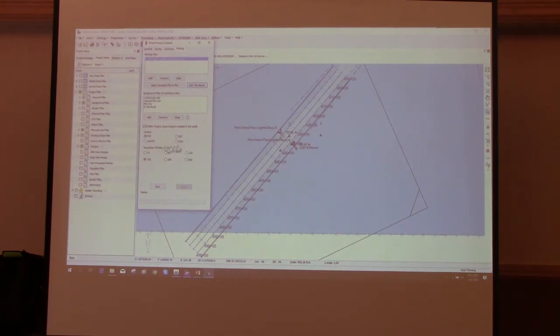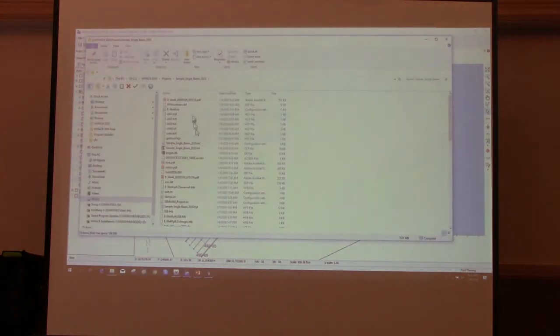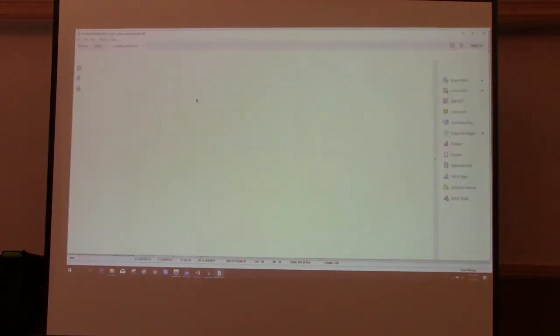So I could send it to PDF, GeoTIFF, DXF, or DWG. So let's do a PDF right now, and I'll do 150 dpi, and click on Run. So it's running through the sorting processes and then the contouring and then finally generating a plotting sheet. So process complete. I'm going to leave that open at the moment and then go to my folder, and I've got my PDF here.